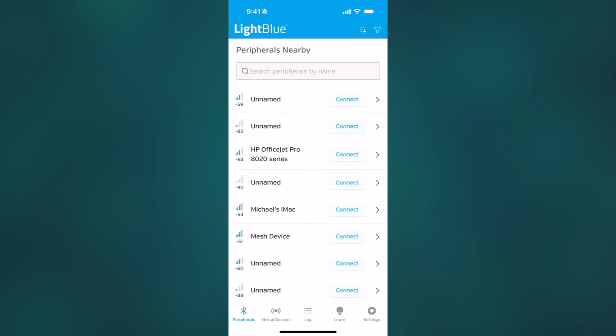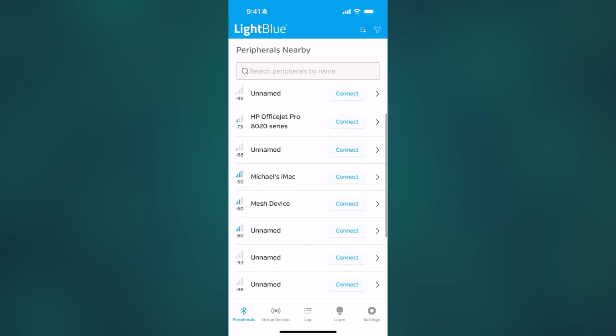Well, here's the deal. What happens when your device gets connected to and then disconnected is that the advertising that we started automatically stops. As soon as a client connects, actually, is when the advertising stops. So if we want to continue to advertise to other devices out there, or to advertise again after one of the devices disconnects, we need to start the advertising again.